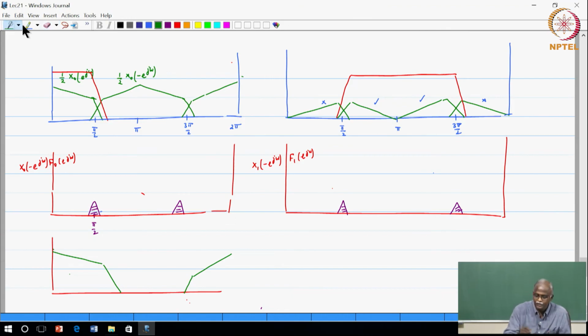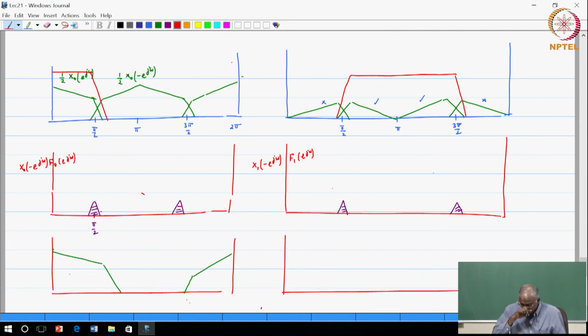From the lower branch, the signal passing through is something that looks like this, and the combination of these two is the resultant reconstructed signal. So, it has all of the frequency components, but the combination of these two may have magnitude distortion, we do not know, may have phase distortion, again that is the part that we would have to deal with.